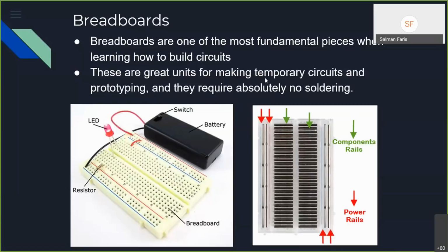Breadboards. So why I introduced the breadboard is that when you do college projects or some small projects, you don't need to make a PCB at the time. So you need to first test your project using a breadboard. Then you can convert the breadboard project into PCB. Okay. So first make sure everything works properly on the breadboard. Then try to convert the breadboard project into PCB. Okay, you can use Arduino for the breadboard, Raspberry Pi and everything, something like that. For the PCB, we don't need to use an Arduino, but we can use the microcontroller of the Arduino, like the ATmega328P or something like that. Okay.